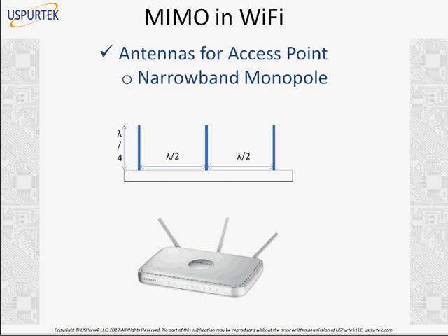Okay, this seems to be a specific problem in the UK. Why a problem with TV frequency in UK? Okay, for LTE. These types of problems happen when the LTE frequency allocation is based on a countrywide basis. When we go to the LTE slide, I'll show you what frequency bands are available in different countries. Sometimes they might overlap. If it is very adjacent to a TV allocation in that country, it might interfere.